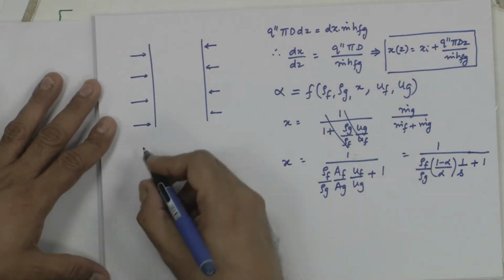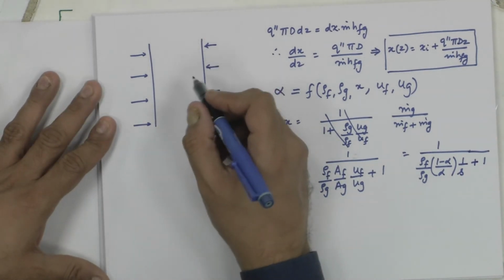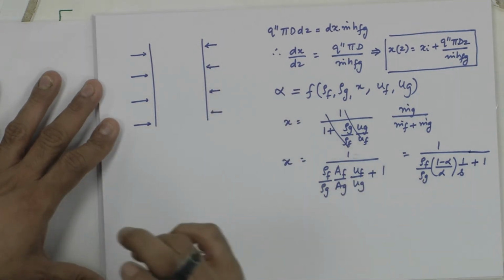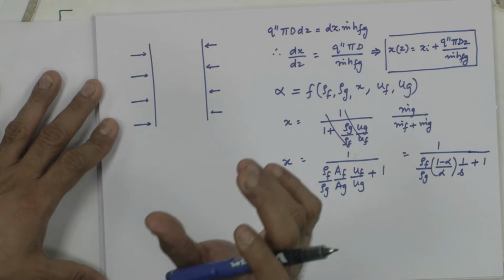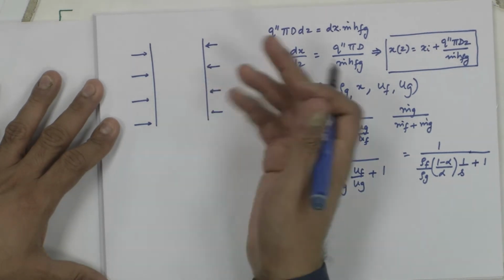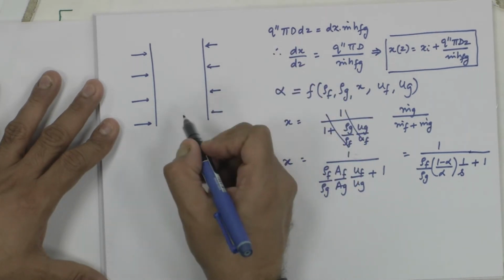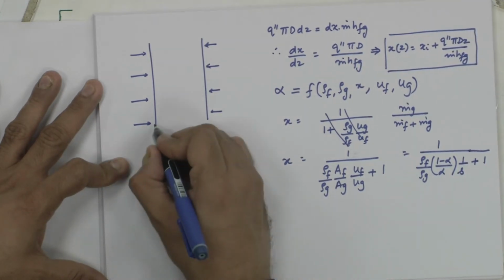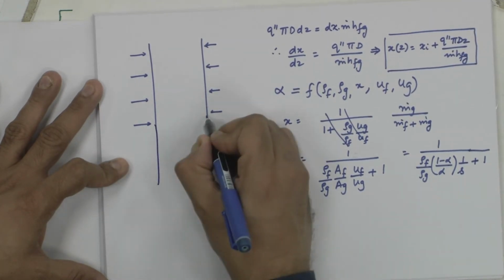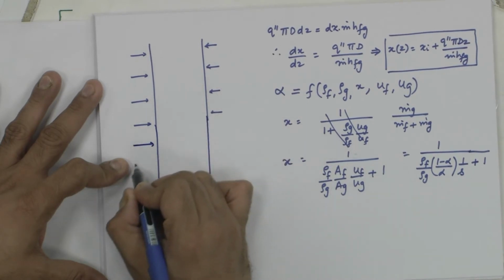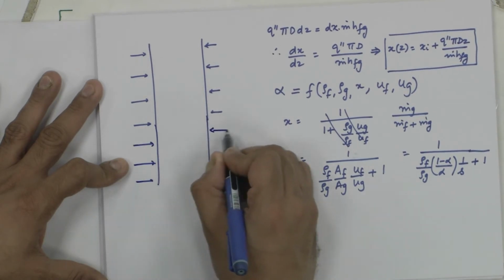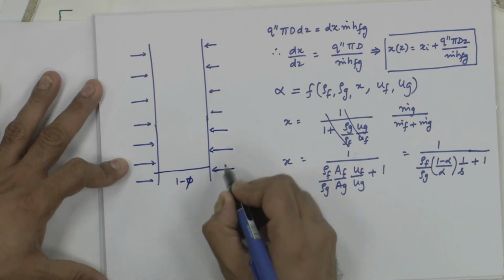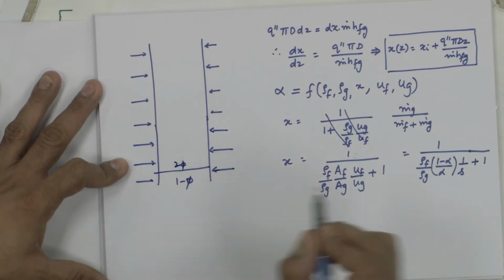Okay. Now, what happens is that when we discussed the introduction to boiling, we said that the nature of the flow pattern dictates how the heat transfer is occurring. So, we will quickly say you have initially when you have liquid coming in, if this pipe is very long, we do not worry about the length, and if the liquid is coming in as subcooled liquid, you would have a single phase region in the subcooled part, then you have a two phase part here.